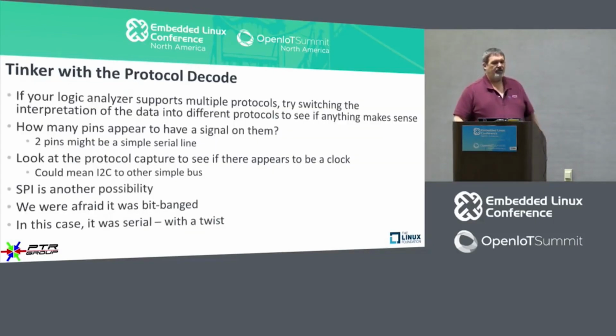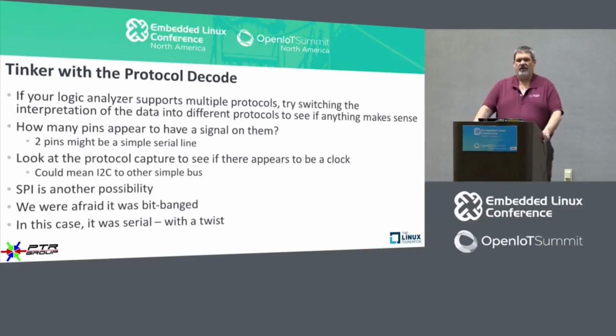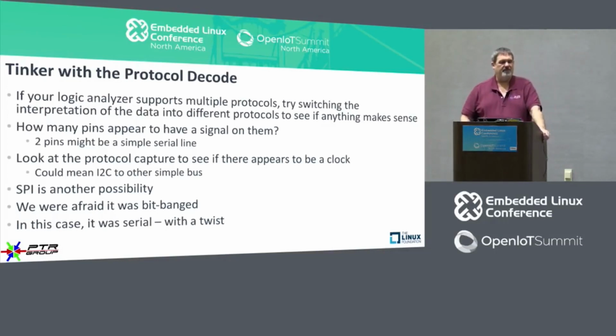Now, when you're trying to do a protocol decode, if your logic analyzer supports multiple protocols, try and switch. You've captured the data, just simply switch the interpretation. If you look at it as CAN bus, if you look at it as I2C, if you look at it as normal RS-232 async, those kinds of things can be really helpful just to be able to see it.